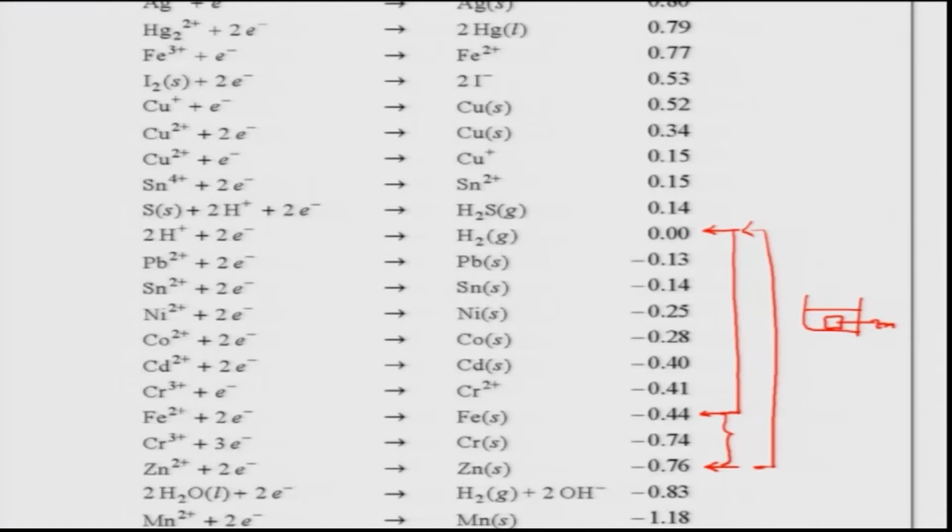So, now you can see that if we choose any of those pure elements and club it with another element where the reduction potential is below the earlier one, then the earlier one will act noble and the bottom one will act active in that particular couple. So, that information definitely we can get from this, but remember this is for pure metal.